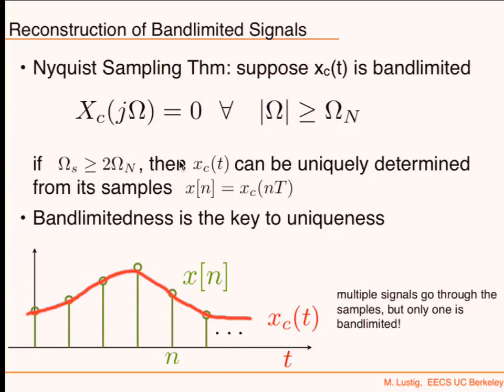Yeah, so you can look at a sinusoid example. Sinusoids start at 0. If I sample, what's the rate that I need to sample it? It's basically every half cycle, right? But the problem is that if I sample a sinusoid at every half cycle, 0, 0, 0, it doesn't work. For cosine, it works: 1, minus 1, 1, minus 1, right? So you just need a tiny bit over in order to see this change. Okay, that's basically the intuition behind that.